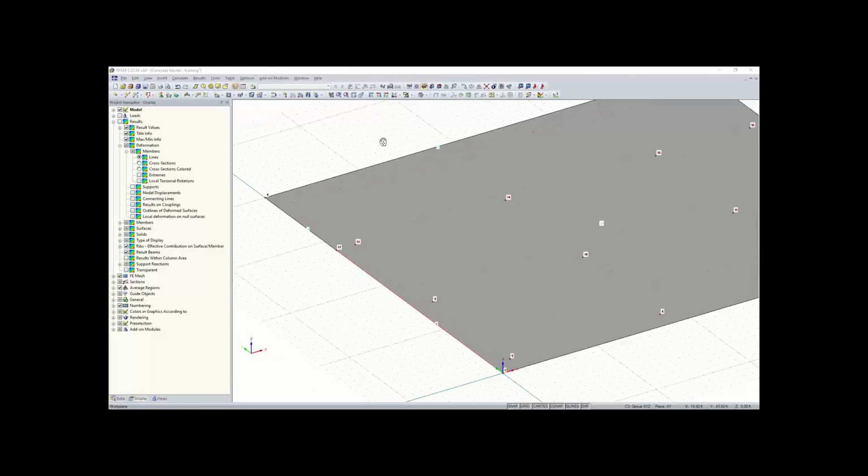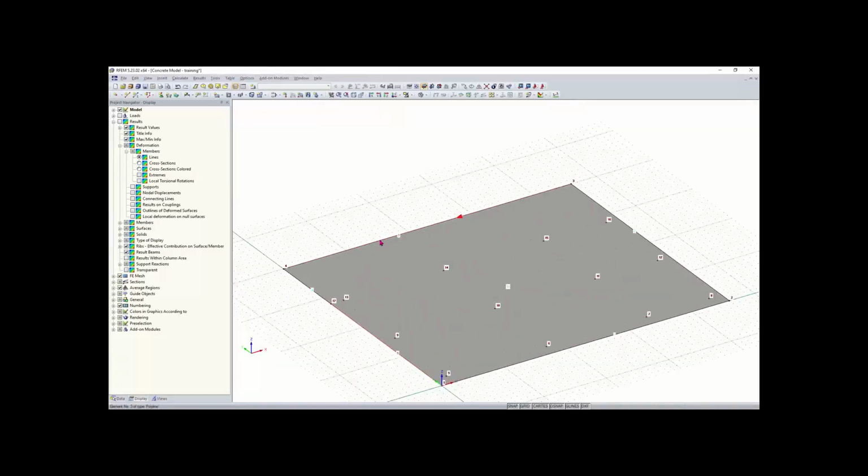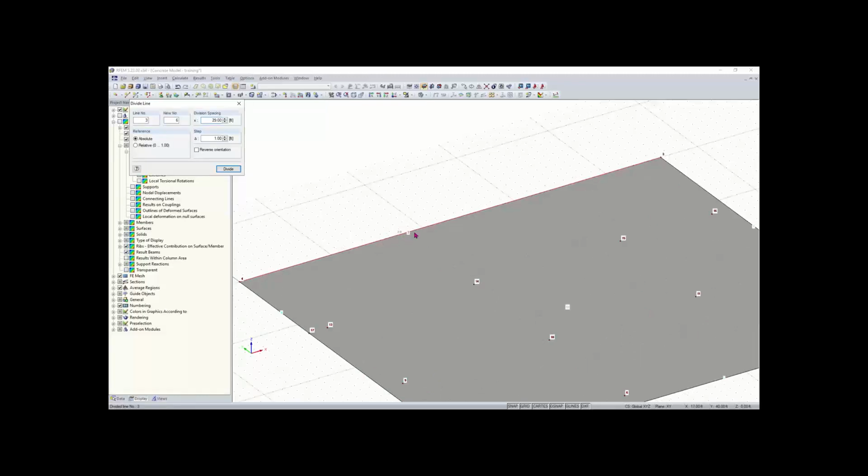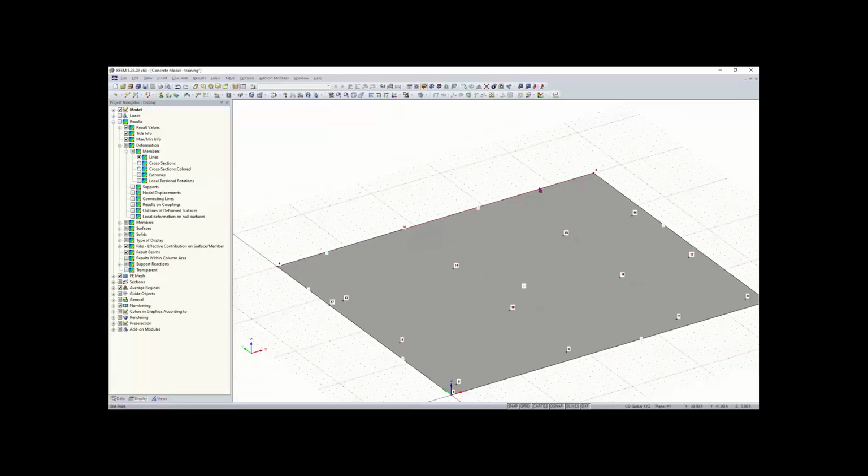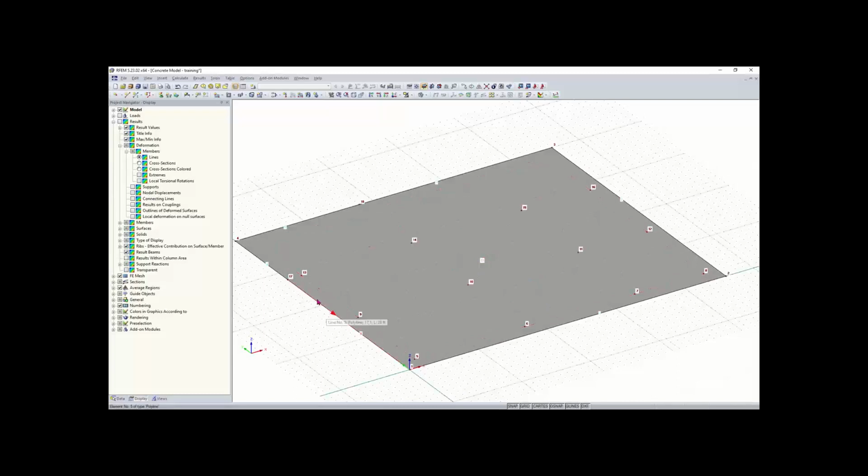And now we can do the same thing for this line up here at the top. I'm going to click on it, right click, select divide line graphically. And maybe just to reiterate what graphically means, you can see I can just snap or place the node wherever I want to on the line using my cursor. I'm going to place it right here. This is going to be 28 feet from the start. So I'll place that, and now you can see that we have 2 lines now with the node placed at 28 feet from the start. And also again, if you're confused about the orientation of your line, you can see the arrow here. When you hover over your line, this red arrow tells you the direction.